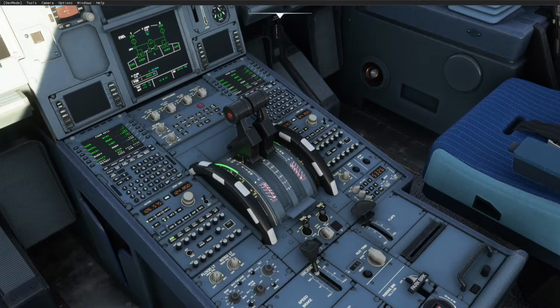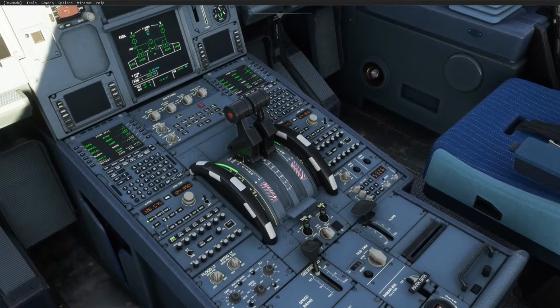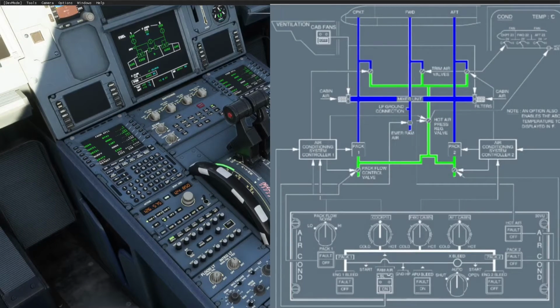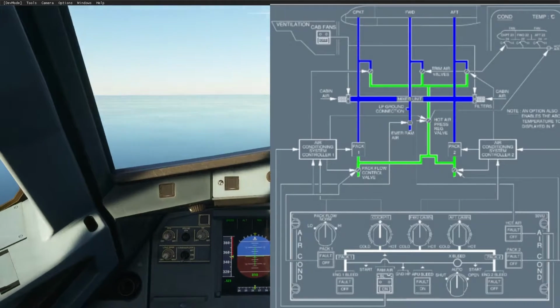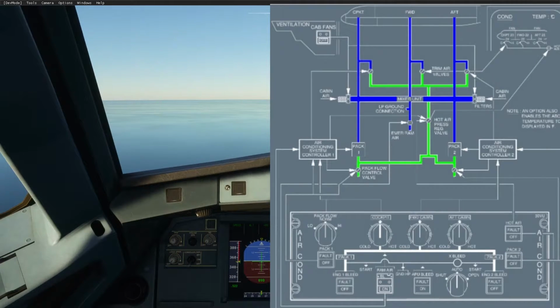So, let's talk about the ACSCs that we've been talking about so much. These are the controllers that control the air conditioning system, funnily enough. The air conditioning system controllers. They're both automatic. We have sensors that will monitor the temperatures, and they're located in the cockpit, in each of the lavatory extraction circuits, and also in the galley ventilation. They use this to then supply air at a relevant temperature for the demand being asked.